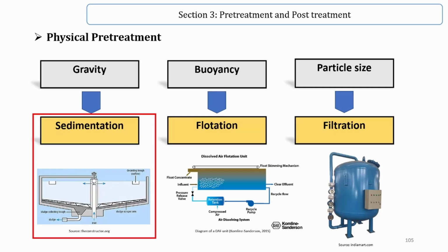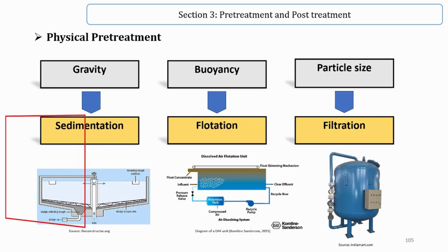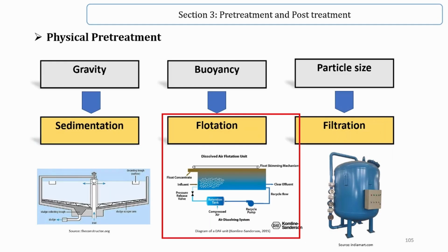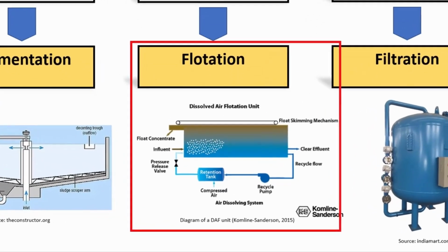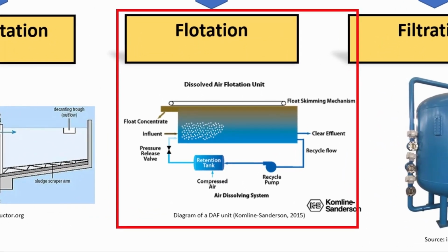Solids with low settling velocities cannot be effectively separated by sedimentation because this would require very large sedimentation tanks. In this case, flotation processes provide a sensible alternative. The basic principle is still the same. Gas bubbles attach themselves to the bottom of the solids and drive the solids to the surface. Once there, the floated solids can be removed with special scrapers. Flotation processes differ mainly in the way the gas bubbles are produced.